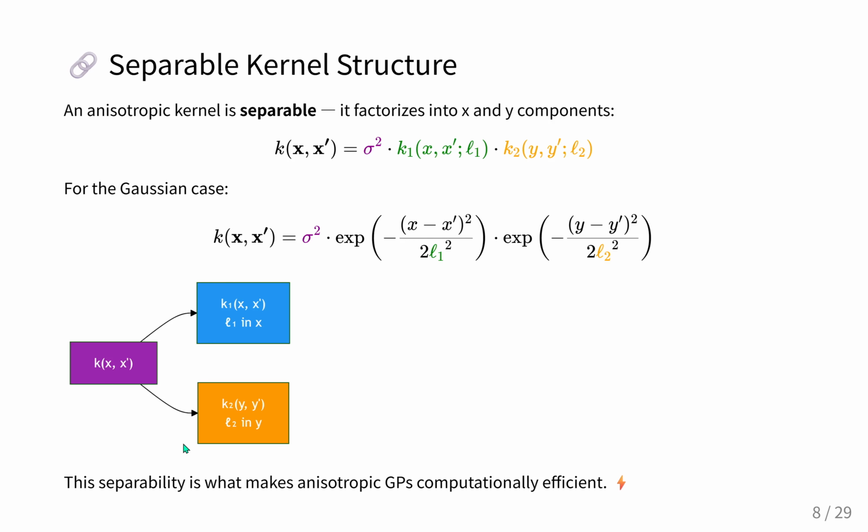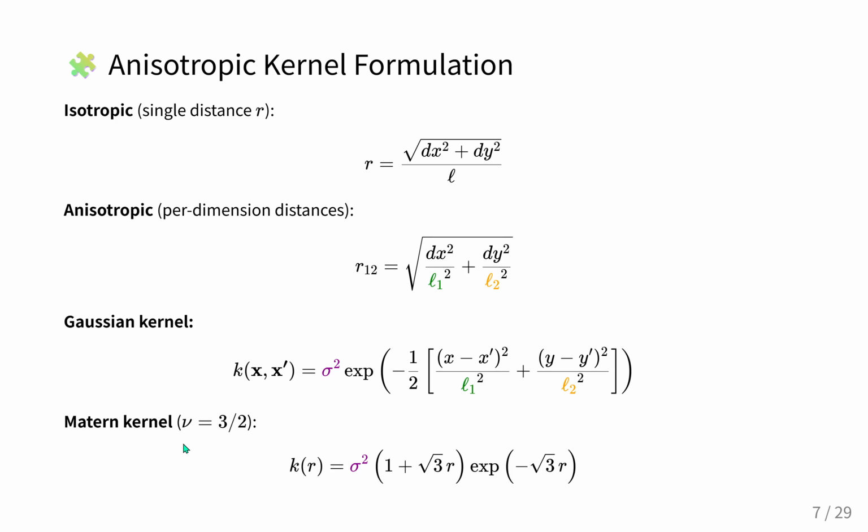And the reason the presentation mentions different types of kernels is that real-world manufacturing data isn't always perfectly smooth. Right. A Gaussian kernel assumes the physical variations are infinitely smooth and gentle like rolling hills. But Matern kernels are designed to handle rougher, more abrupt changes in the data. They are much better suited for the harsh physical realities of, say, polishing metal on a wafer.